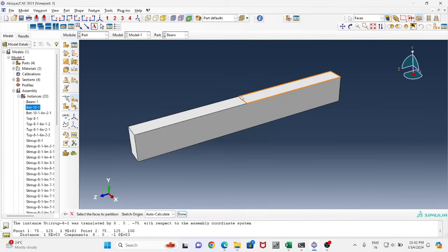It's not always that you have to put a line. Sometimes it's a space or an area. It depends on what kind of loading it is and how it's applied to the concrete. So just be careful. It's not always recommended to put a line. It depends on how the load is being applied on the surface of the beam. Anyway, for this example, I choose a line.